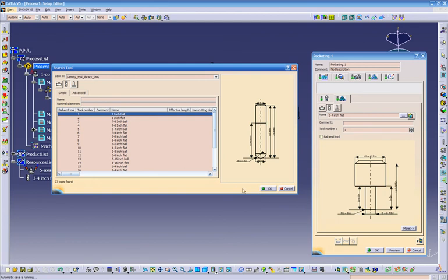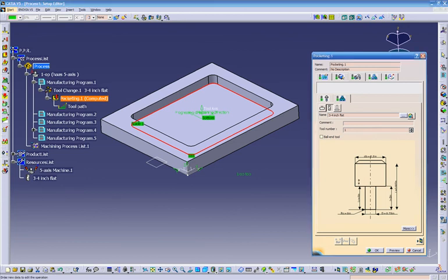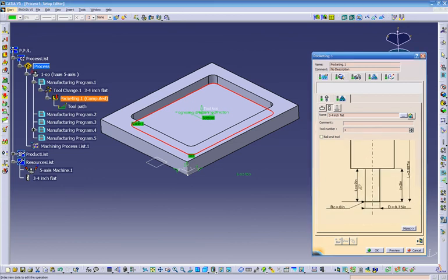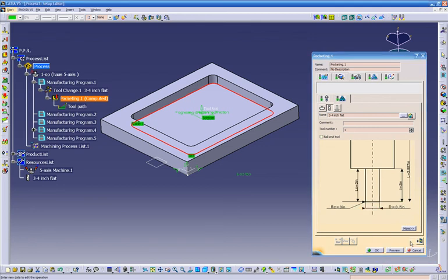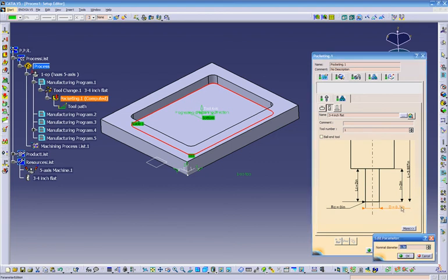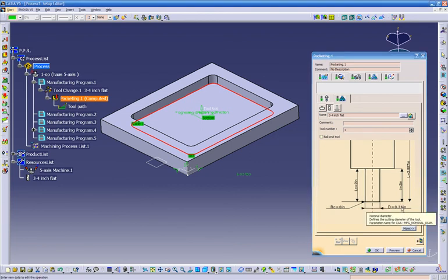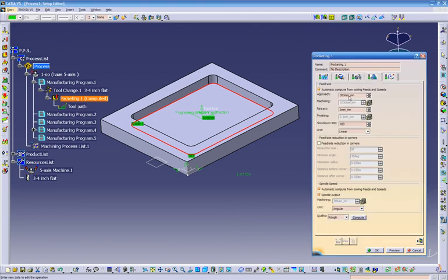So click whatever tool you want, and then you click OK. Then you get a tool over here, and you can customize it, the tool length if you have radius, and also you can change diameter. You can change it to 700 if you want. Okay. So let's go next. Next is our speeds and feeds and speeds.